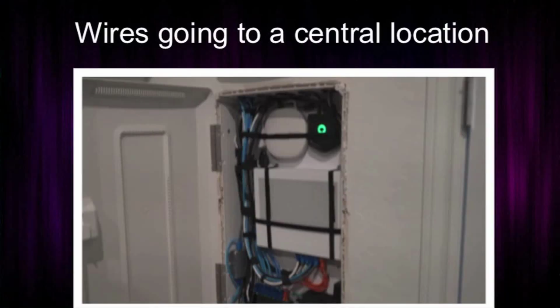Now, these Cat6 cables are routed along the length of the routing area from the NVR to the CCTV camera using suitable conduit, and then the wires go to the central location where the NVR is placed. Usually the wires are routed through a distribution frame like this, which can be a flush mounted or wall mounted type frame or rack, installed near the NVR as far as possible so that the connection from here to the NVR is easy.